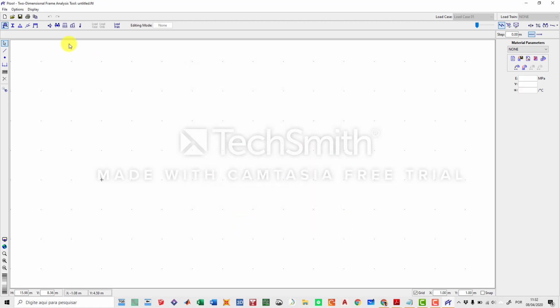After that, you can see the other parts of the interface. Here at the top, you can set up the material properties, so you can tell Ftool what materials you're going to use. You can declare steel isotropic or concrete isotropic. The second part is section properties. So you're going to create a section, which can be a square section, a rectangular section, an I shape, or a predefined I shape from the industry. Ftool comes with that.